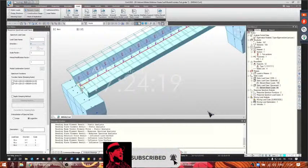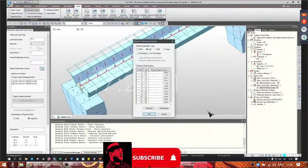Here we can choose the way we want to combine the modes. A preliminary operation before defining the RS load cases is to define the number of modes that you want to be considered by the program in the eigenvalue analysis options. Otherwise, here we won't have any mode to combine. We chose the CQC combination since we expect close natural frequencies between modes.